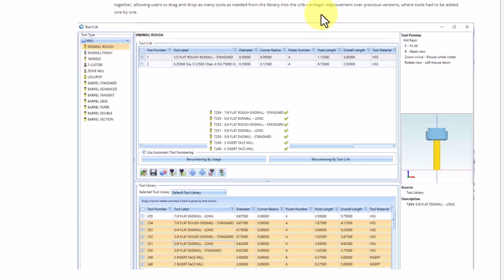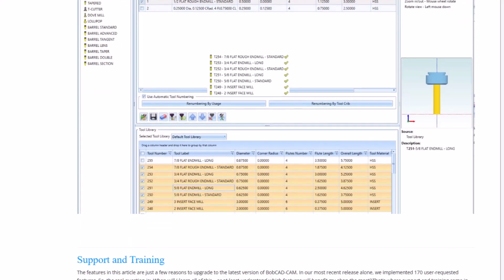And lastly, the tool library and tool crib. They've improved this too. You can now create multiple separate tool libraries. Maybe one for metric tools, one for standard, one for a specific machine. Better organization. And getting tools from your main library into the crib for the current job used to be one by one. Now you can just drag and drop multiple tools at once. Much faster setup. Right, just streamlining every little step.